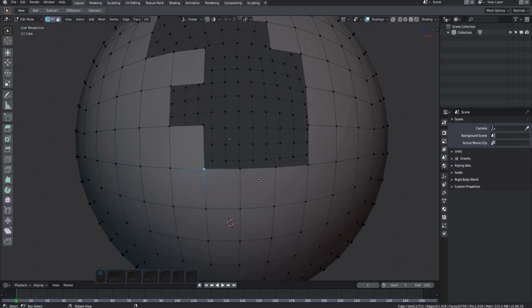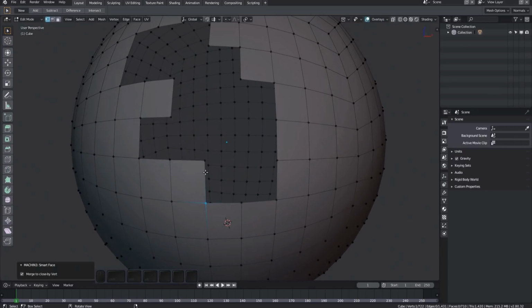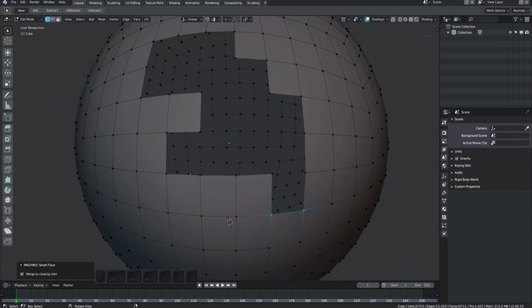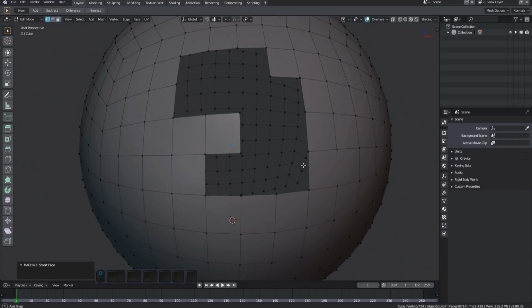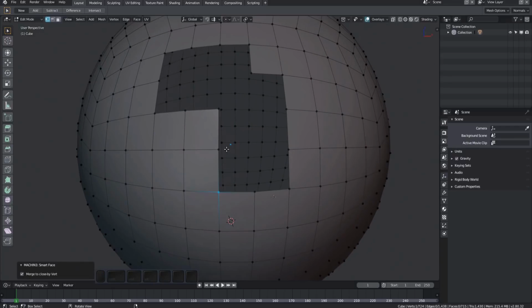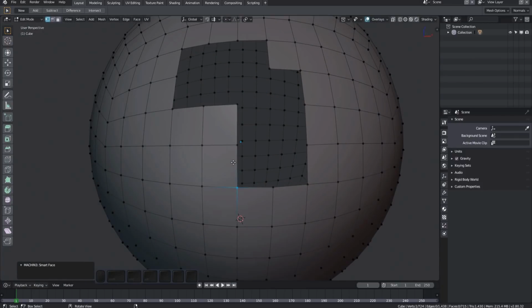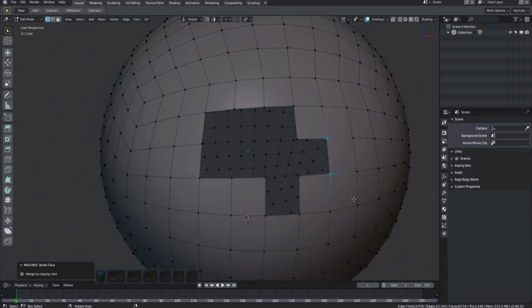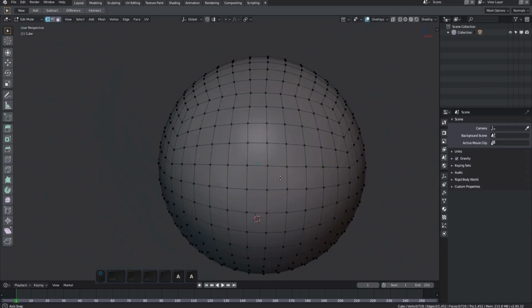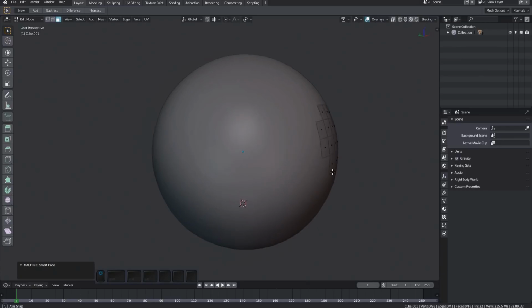To create a face, select a single vertex in a negative corner like this, and run the tool. Smart Face will try to make a new selection afterwards, so you can run the tool again immediately. If the proper topology can't be found, nothing will be selected. Even in a case like this, only a single vert selection is necessary, as long as the merge property is enabled. Otherwise, a 2-vert or an edge selection is required to close the face properly. If you run the Smart Face tool on a face selection, a new object will be created from those faces.